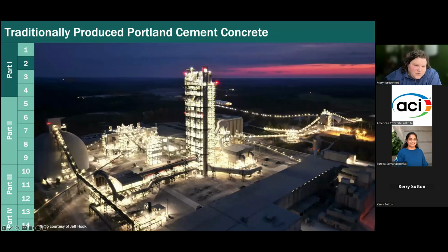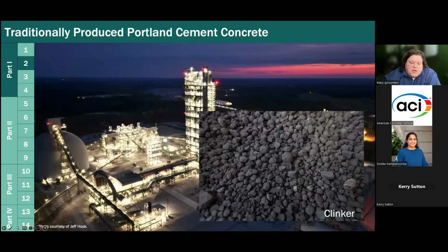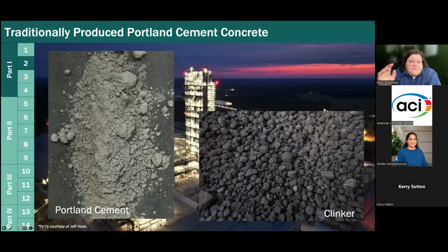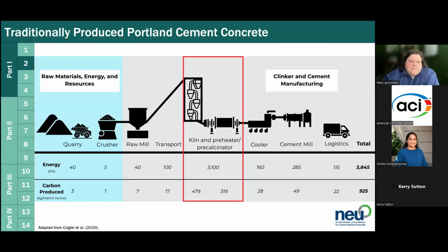They slowly go through the kiln, a whole bunch of chemical reactions happen, and eventually these raw materials turn into clinker. Clinker is what comes out of the kiln. Now the clinker is cooled down really quickly, and then it's ground together with gypsum, and then you get Portland cement, which of course is the gray powder we're all familiar with. So chapter 2 goes through this procedure and explains all of the technology and the vocabulary.